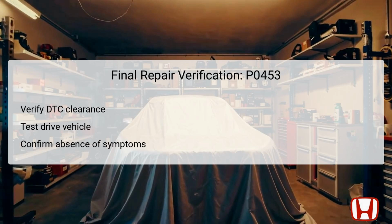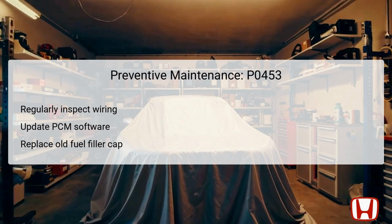Following this verification, a test drive of the vehicle is necessary to observe whether the symptoms associated with DTC P0453 persist. Focus on checking for any occurrence of the check engine light and monitor for improvements in fuel economy and engine performance. If multiple drive cycles occur without reactivation of the DTC or any symptoms like rough idling, the repair can be considered successful. Preventive maintenance is crucial to the ongoing reliability of the FTP sensor system and can help avert future occurrences of DTC